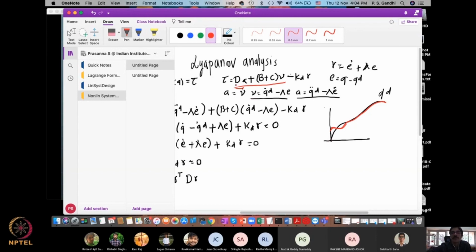Okay, these are feed forward terms that we are using, and then this is a feedback term. So this Kd and r, this is a feedback term. So we are using a combination of feed forward term and feedback term here to drive. So this term will take care of most of the control action to get to this trajectory.